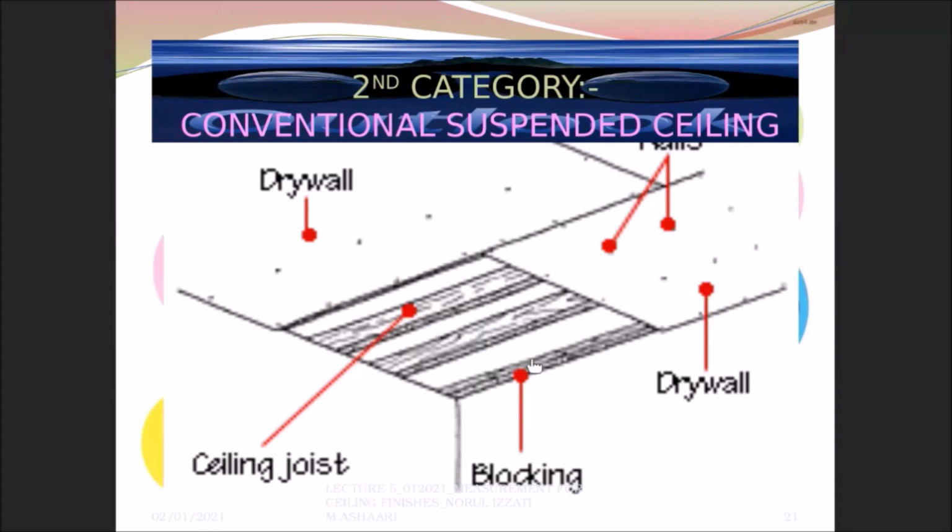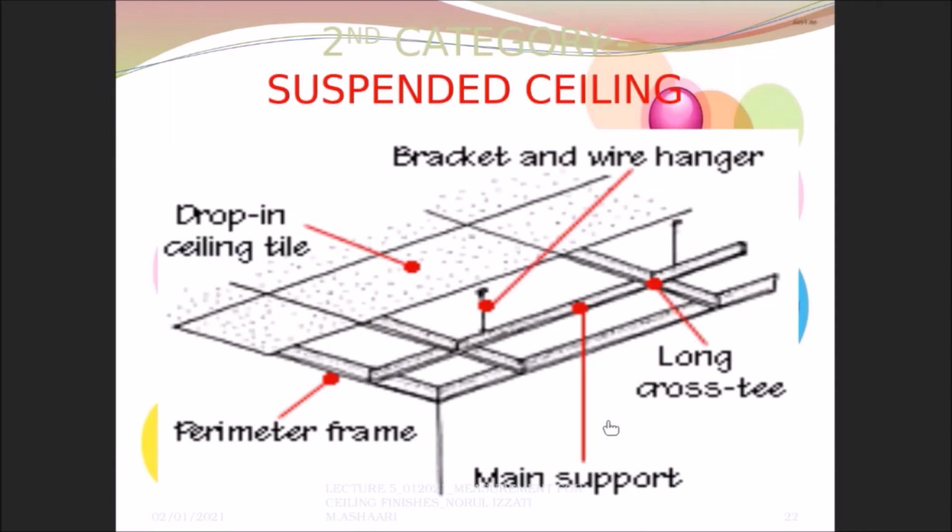Okay, so this is the ceiling joist detail that is made from timber. Conventionally, the method is using timber. So whether you need to measure this one or not, it depends on the detail. Normally, this ceiling joist is not to be measured under ceiling unless it is put in the specification where drywall comes together with ceiling joist. That one you have to measure under one item. Okay, if not, the ceiling joist is not to be measured.